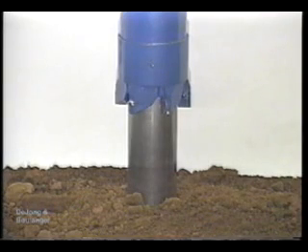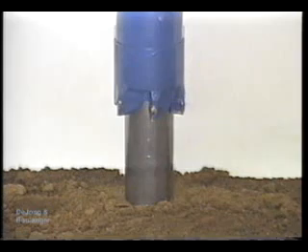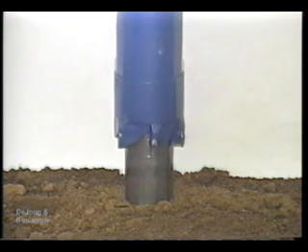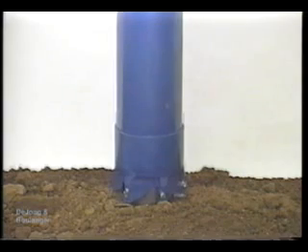If the soil is soft, the spring at the head of the tube keeps the cutting edge of the tube below the cutter barrel, and the tube is pushed into the soil, just like ordinary tube sampling. If the soil is hard, the spring is compressed until the cutting edge of the tube is forced above the bottom of the cutter barrel. As the barrel rotates, it cuts an annular ring, leaving a cylinder of soil over which the sample tube slides. The tube thus protects the sample against erosion by the circulating fluid. In this manner, the pitcher sampler adapts itself to the stiffness of the soil.